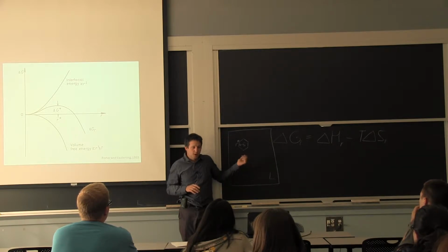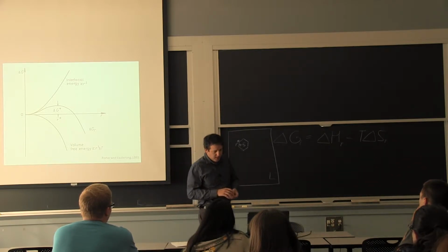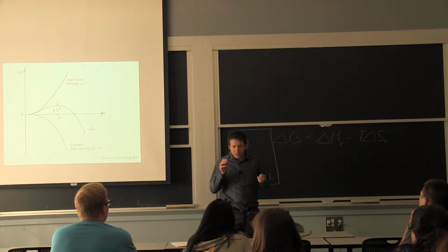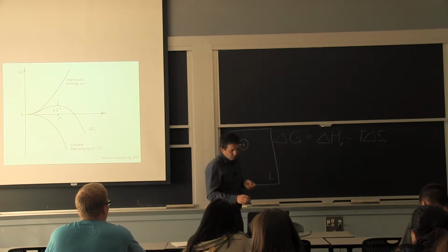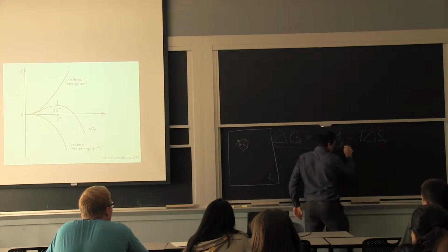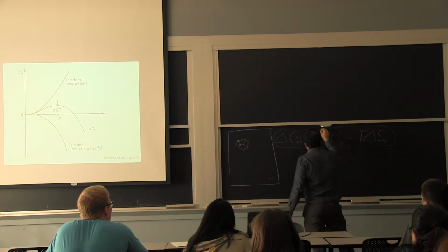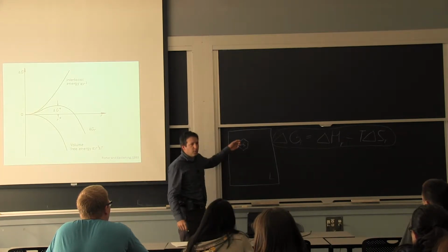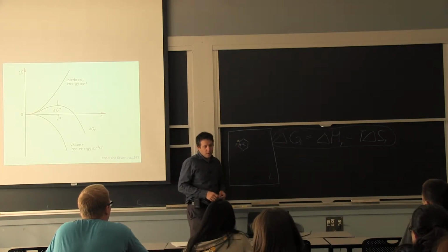So this is a general concept, but it ends up being helpful in our context for solidification, thinking that even though I reach the critical temperature where this equation says it's 0, I still need a way to go from the liquid to the solid, and that's by forming this nucleus there.